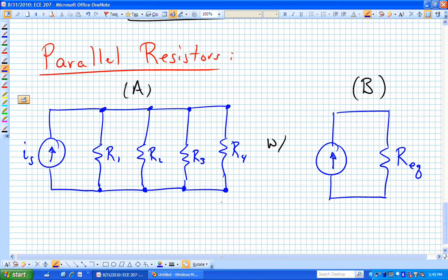So we can't necessarily go up and say, oh, well, let's just do the voltage drop across that source. We don't know what it's going to be. So you don't do drops across the current source. Just like you don't do currents in or out of a voltage source. Did I say that wrong? Current source, you can't do KVL. Voltage source, you don't really do KCL with. You don't know what the current is. The current's going to be what it's going to be for a voltage source.